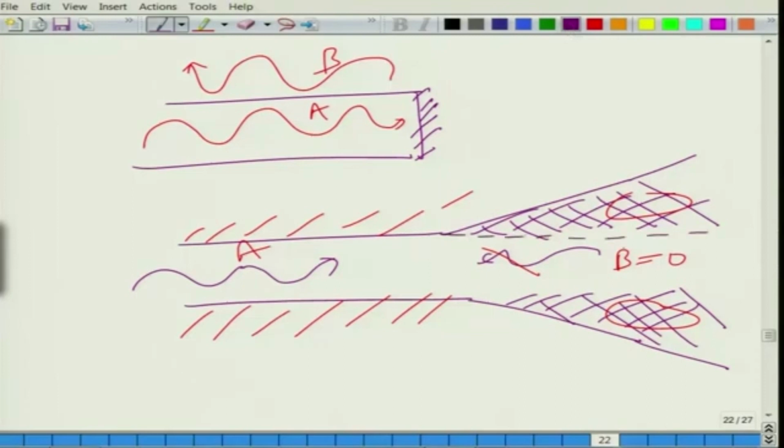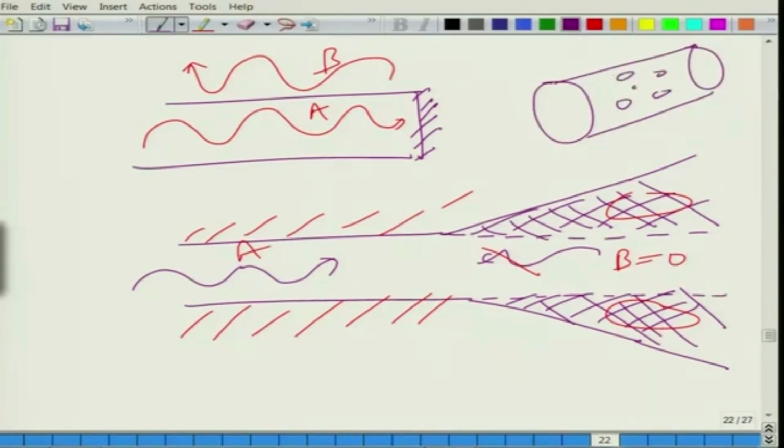So, you see a perforated tube. Typically by perforated we mean these small holes will be there along the curved surface area. The waves going inside can interact with the stuff that is outside through these holes. That is what is going to happen here. The waves enter these holes and they get dissipated. Most of the acoustic power is dissipated.